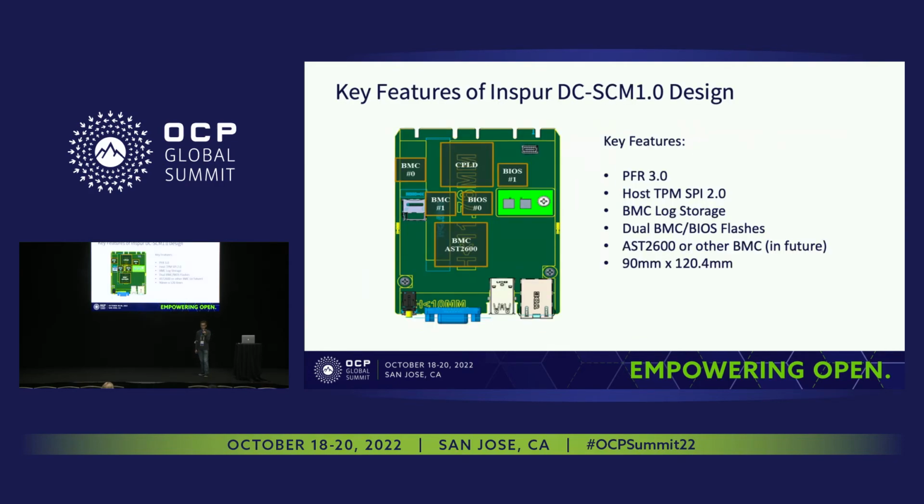A little detail about that: we support PFR and also have the dual BMC and BIOS flash. Ideally, it's not necessarily based on an AST2600; it could be another vendor of choice for our customers to choose from, and then take advantage of the DCSCM concept.